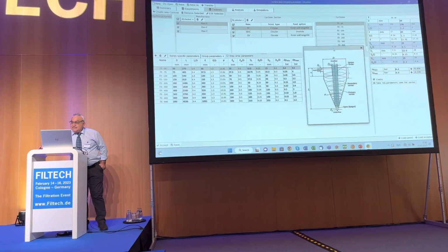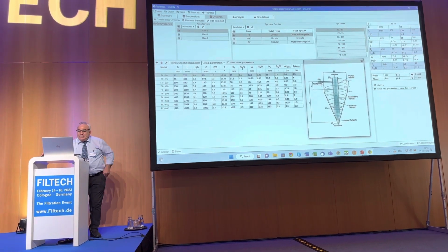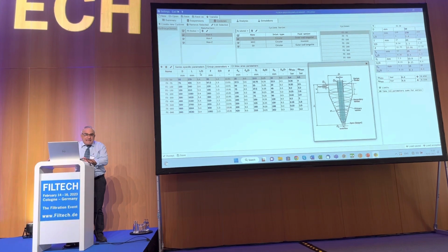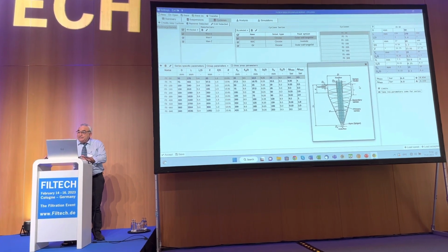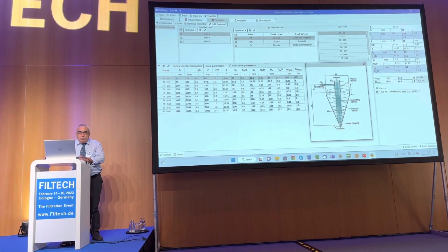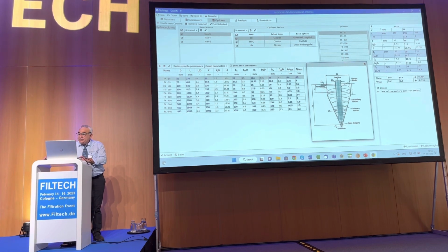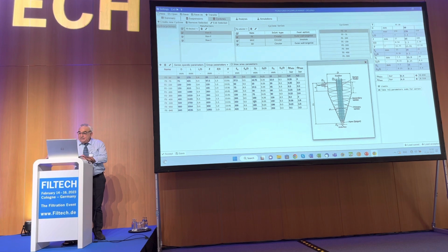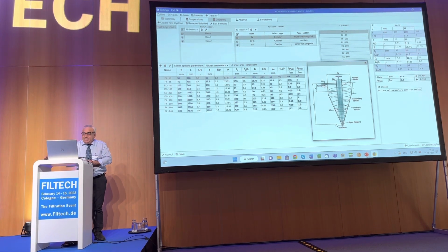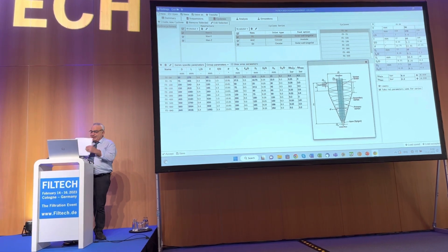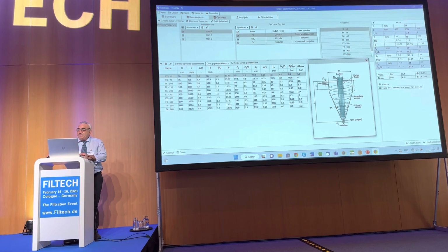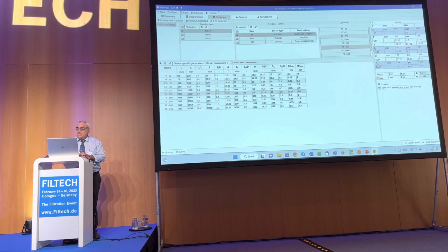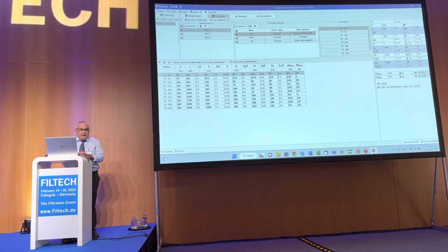The same specific parameters, like here you see, total length over the diameter of the cyclone, cylindrical diameter, and so on. Angle here, that is the angle of the hydrocyclone. These are the relative parameters, approximately the same, not depending again on the diameter. You see here the different cyclones of the same family.